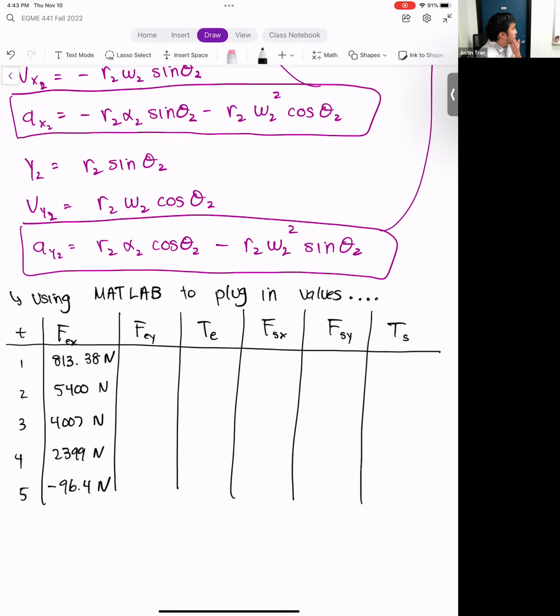And so earlier today, there was a question of, what if you chose different directions for the joint reaction forces? All that would change for your solution here is the sign. When we started at the lower arm, we chose negative directions for the elbow X force and the negative direction for the elbow Y force. If you had chosen the positive directions, it would just change these to positive instead of negative. You'd get the same magnitude, it's just the direction would be opposite. Assuming that you were consistent in making them the opposite direction on the adjacent segment.